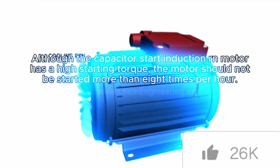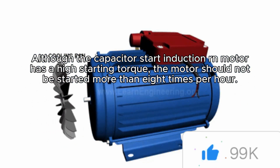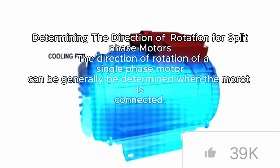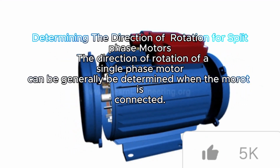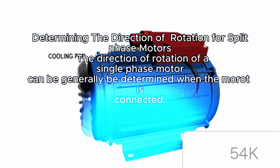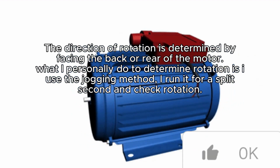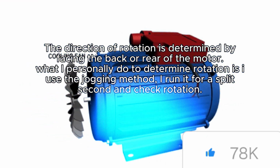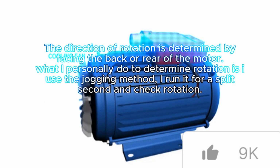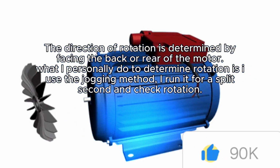Although the capacitor start induction run motor has a high starting torque, the motor should not be started more than 8 times per hour. Determining the direction of rotation for split-phase motors. Direction of rotation of a single-phase motor can generally be determined when the motor is connected. The direction of rotation is determined by facing the back or rear of the motor. What I personally do to determine rotation is I use the jogging method. I run it for a split second and check rotation.